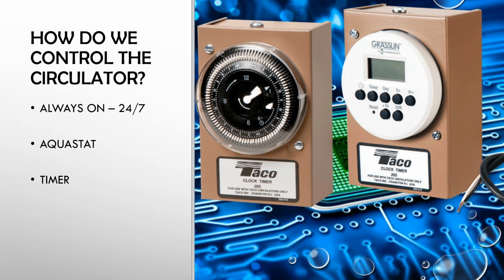And here you can see a couple different ways to do it. We have a standard 24-hour day timer, and each one of those pins that you see here on the analog side represents 15 minutes of runtime of the circulator itself. So if you take a shower at 7 a.m. every day, turn it on a little before and turn it off a little bit afterwards. The digital timer on the right-hand side gives you a 7-day calendar. So now you have flexibility instead of the same schedule every day, because the weekends come along and we might need to change some things up. So you've got your options to control your circulator.